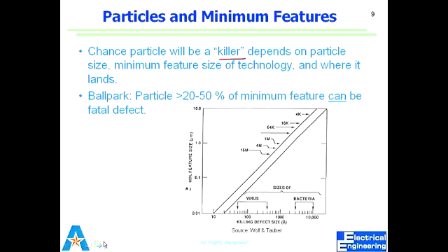Now there are a few new terms here. What is minimum feature size? As a designer, I make all sorts of components, resistors, capacitors, right? Channel length, source and drain. There is always something that is smallest in feature size, which I want to be transferred faithfully from mask to wafer. So that is the smallest feature size, and that will define what technology I will use, so what node I will use, so to speak. Like we discussed, there was the 65 nanometer node, and so that minimum feature size will define what particle size can be allowed in that room.